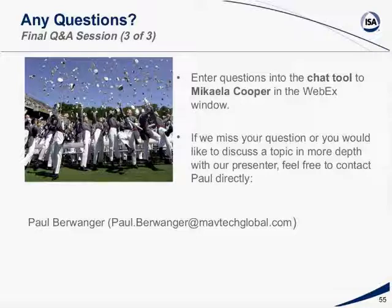And you don't want to have multiple operators being responsible for acknowledging the same alarm, because what ends up happening is operator A will assume operator B is acknowledging it, and vice versa. So you want to have that alarm show up really just to one operator, so you don't have any confusion as to whose responsibility it is to acknowledge and address that alarm.